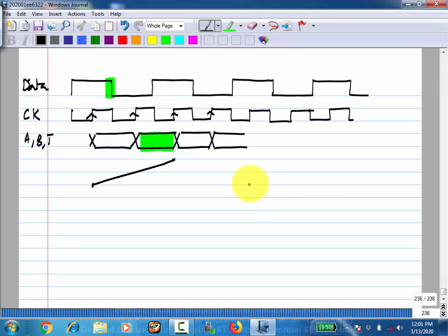It will ramp up and then ramp down for 2 cycles and ramp up for 2 more cycles and so on. Okay, and we were able to calculate the peak to peak value here, right? And like I said, if you try to increase the bandwidth, which is basically increasing the product ICP times R times KVCO, this will also increase. So that also limits the bandwidth. You may want a very high bandwidth for tracking jitter in the input data, but if you do that, the systematic jitter generation increases. Okay.